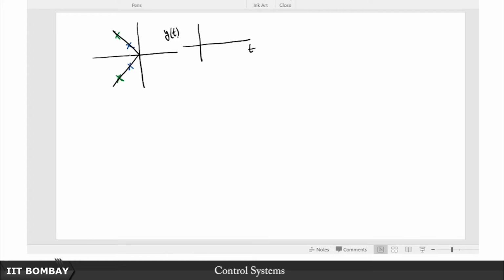First, notice that the real parts of the poles marked in blue are smaller than the real parts of the poles marked in green, which immediately tells you that the settling time for the system marked with blue poles will be higher. In other words, it will be a more sluggish system. We also know this intuitively by the fact that the closer the poles are to the imaginary axis, the slower is the rate of decay, and consequently the slower is the response of the system, right. So now what else can we say about this?